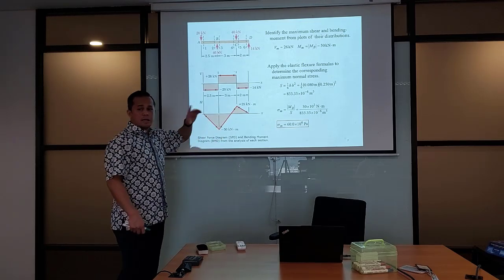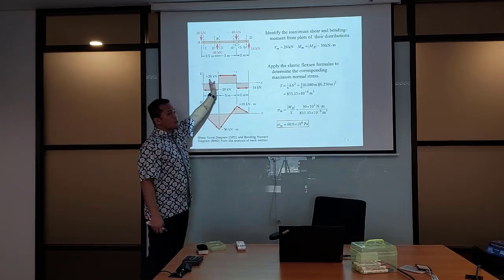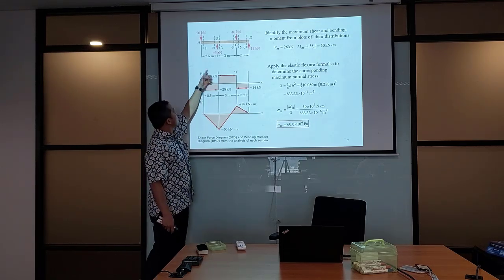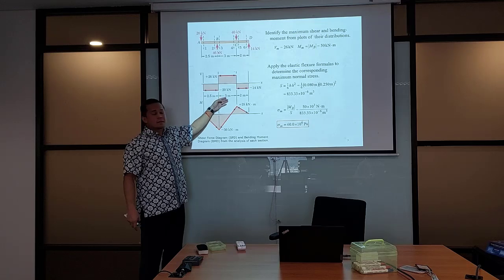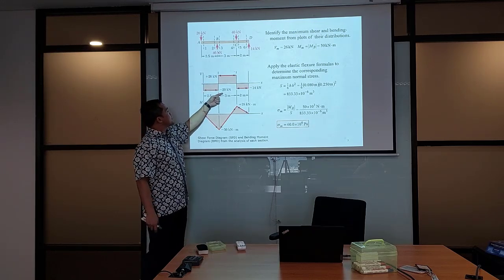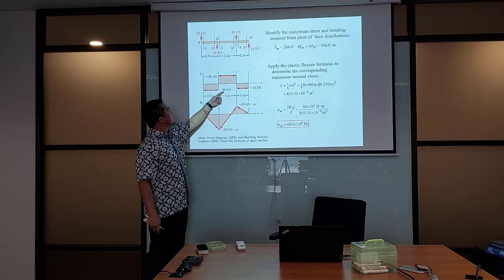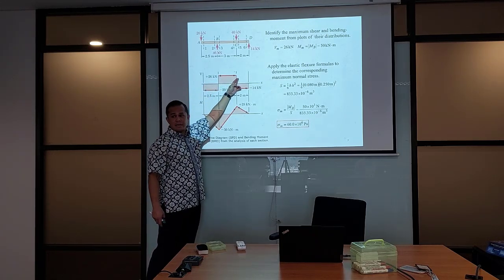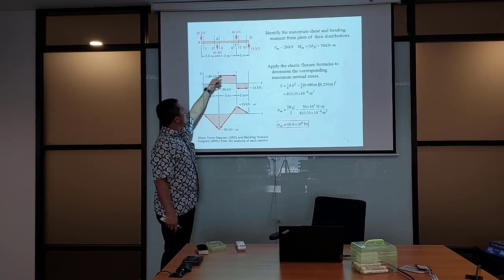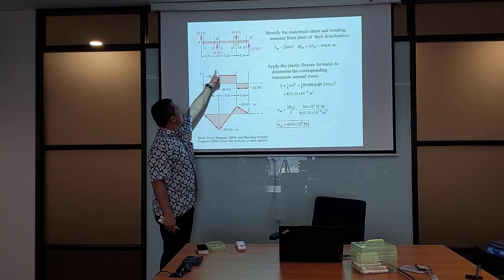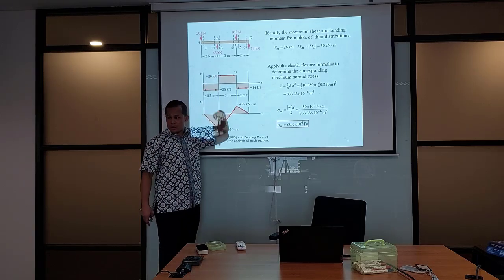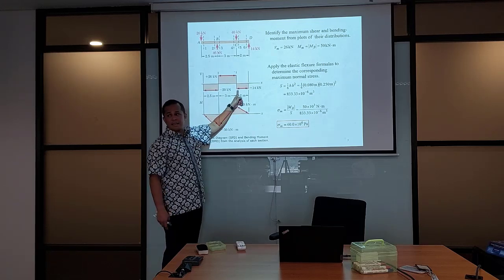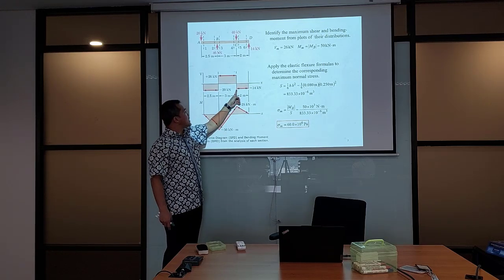And then, a concentrated load. And then no load applied after that. Therefore, no gradient. Gradient is constant again. Because this is minus 20, add up by 46, you are subtracting the 46 minus 20, you get plus 20, 26. And then constant gradient. Another 40 kilonewton going downward, so 26 plus it is 40, it is minus going downward. So 26 minus 40, you get 14 minus 14. And then from 14, no gradient.